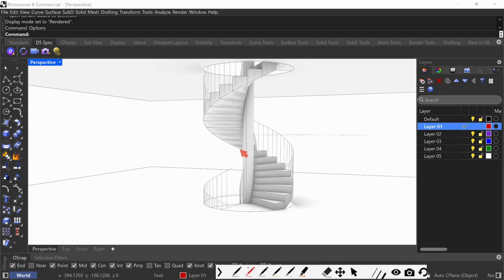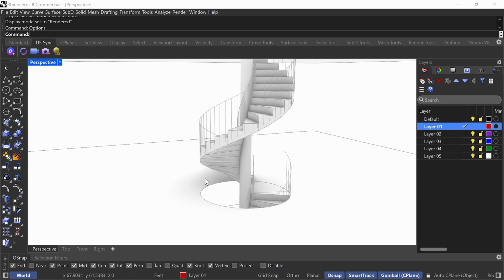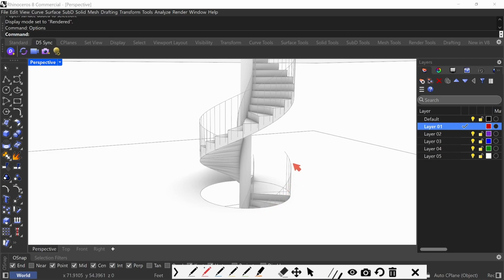So you would have this come out 12 inches and you're landing. And this would just continue like that. And then you would obviously also have a guard over here wherever this is stopping. So sometimes there'll be a double guard here, but you'll have a guard here. You'll have a guard here that goes around like this. Some people will just carry it all the way across like that, depending how you do your spiral staircase.